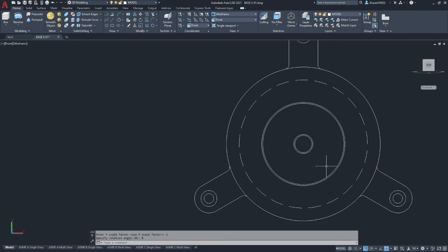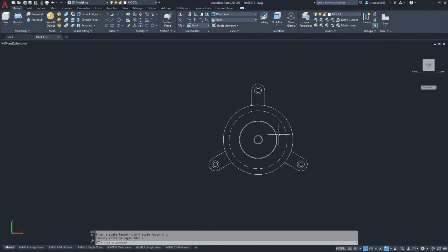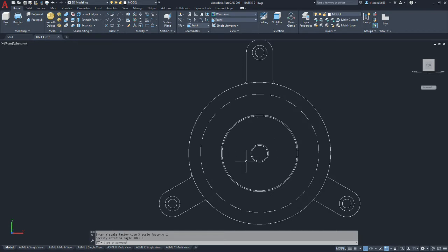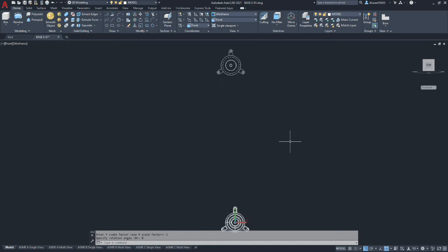view. Now we could interpret it as another hidden line here, but I think due to the taper and the small fillet that's on the inside, it's not picking up on it as tangential edges. At the top end of the cone, and on this edge we're seeing a sharp edge to the back of the part. So we need to manually put in a hidden line for the inside circle if we want to show that as a hard edge.